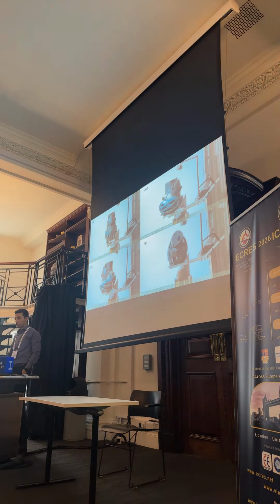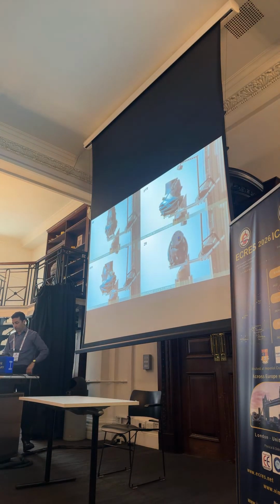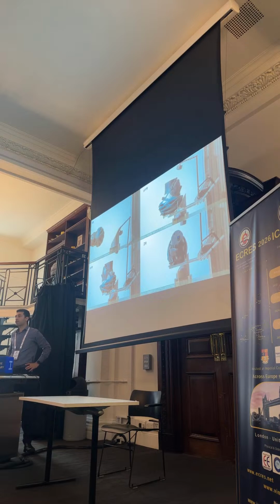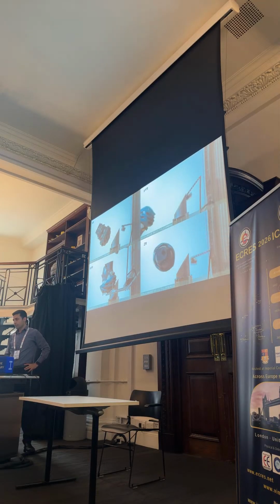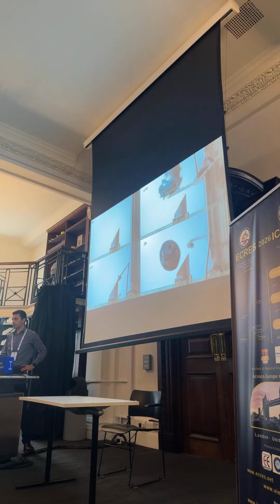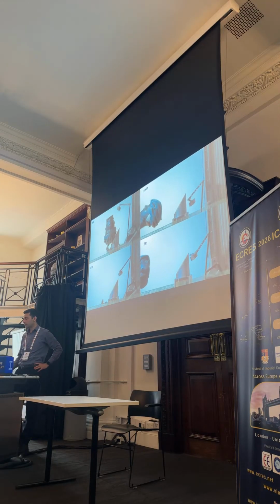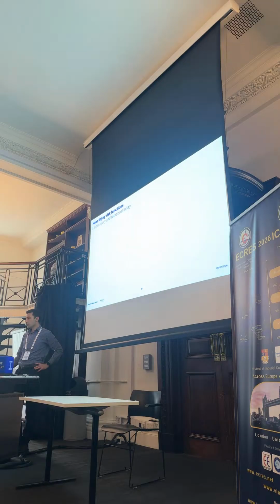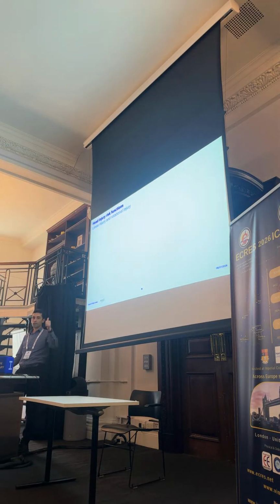So based on that, we set up these impacts. So you can see we do 4 impacts. 1 is on the side, 1 is on the front, 1 is on the front side, and 1 is on the back. So we do 4 different impacts, which is aligned with the new revision of the standard not published yet. And from this, we make measurements. Measurements of linear acceleration, measurement of rotational velocity. So these can represent 2 different categories of brain injuries.